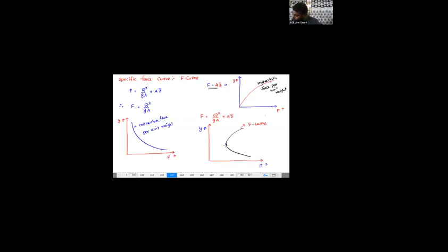Now you see, out of all this, this curve has some minimum force. That is going to be F minimum. And whatever the depth corresponding to the F minimum, this is known as the critical depth. So how do we get to know that F minimum is going to be critical flow, sir? I hope you remember the E minimum, right? There I told you, for F to be F minimum, you simply differentiate the force with respect to Y equals 0.